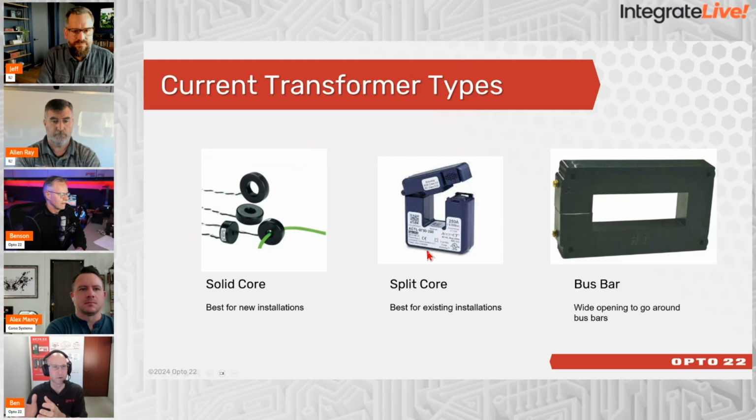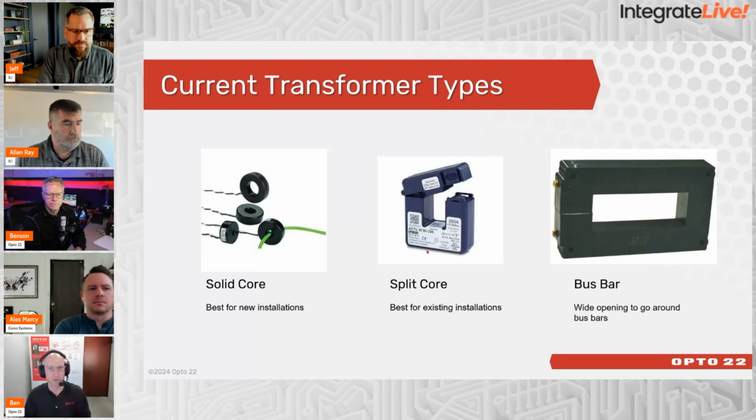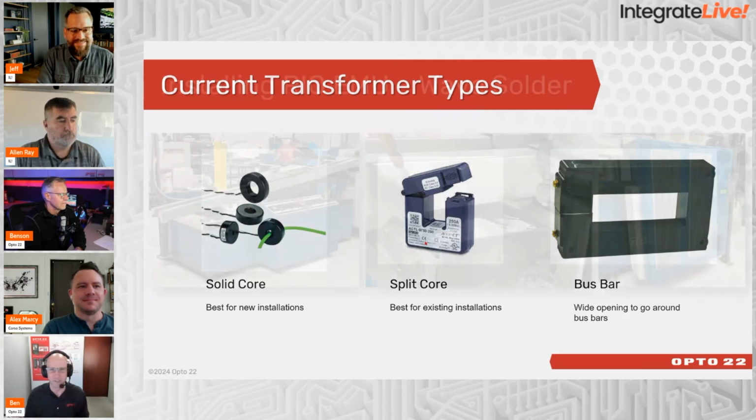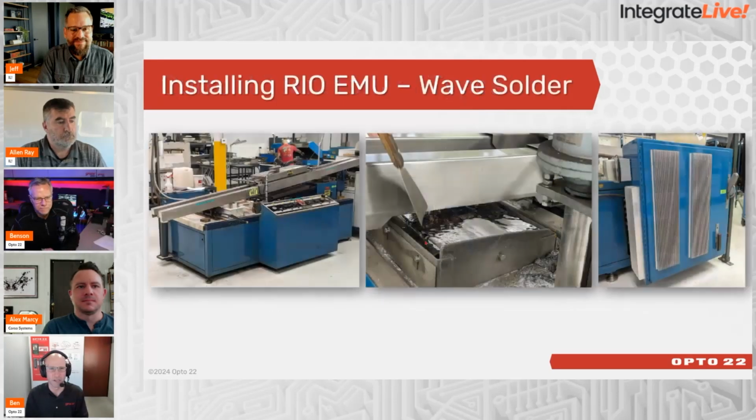That's how we pick up the current of the load, whether it's a building, a sub panel, or an individual machine. In our case, you're going to need 3 CTs for 3-phase, 2 CTs for 2-phase, and a single CT for single phase. So you just pick the rating that you need based on the load. They come from 5,000 or 6,000 amps down to 5 amps. The little 5 amp ones are pretty cute. They're handy for monitoring a PC or a small load, something like that.